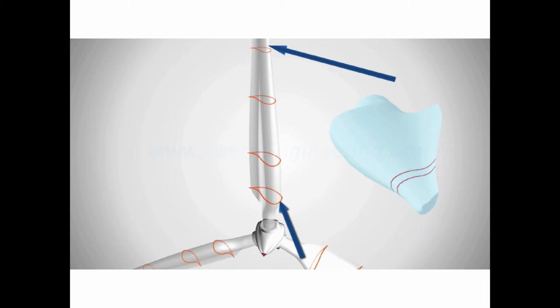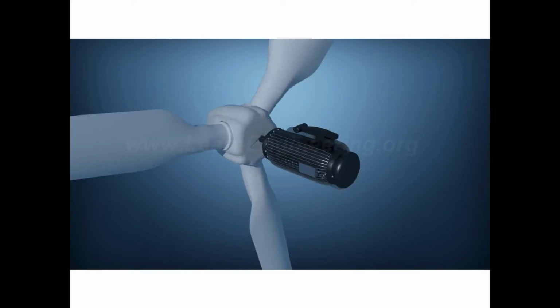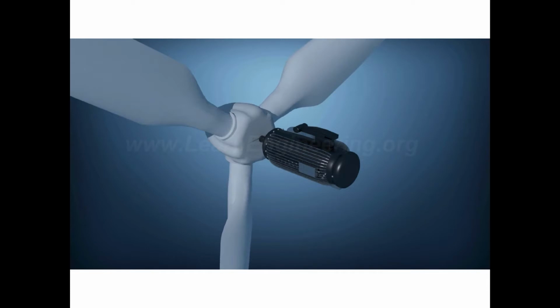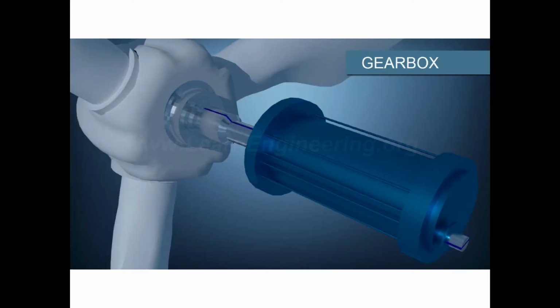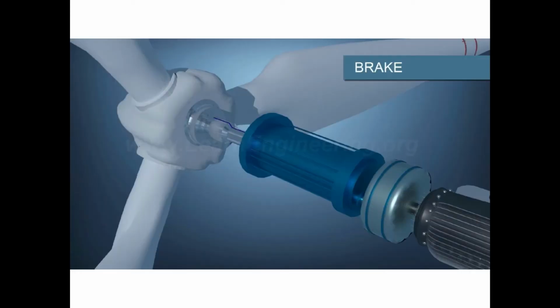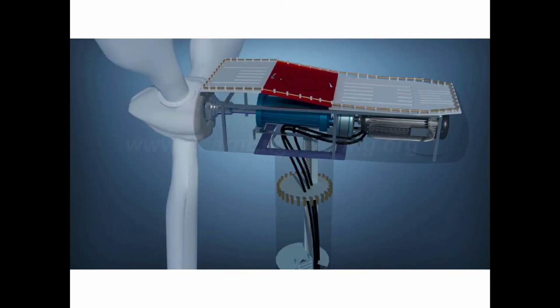However, this rotation cannot be directly coupled to a generator because wind turbine blades typically turn at a very low rate of RPM due to the issues of noise and mechanical strength. Considering this slow speed rotation, we cannot produce any meaningful electricity frequency from the generator. So, before connecting to the generator, the speed is increased in a gearbox. The gearbox uses a planetary gear set arrangement to achieve the high-speed ratio. A brake also sits in the nacelle. The function of the brake is to arrest wind blade rotation during excessively windy conditions. Consequently, the electricity that is produced is transferred through the cables towards the base, where a step-up transformer is situated.